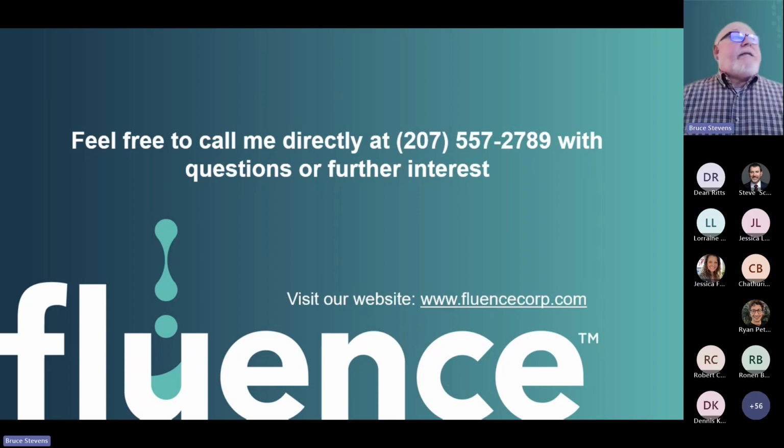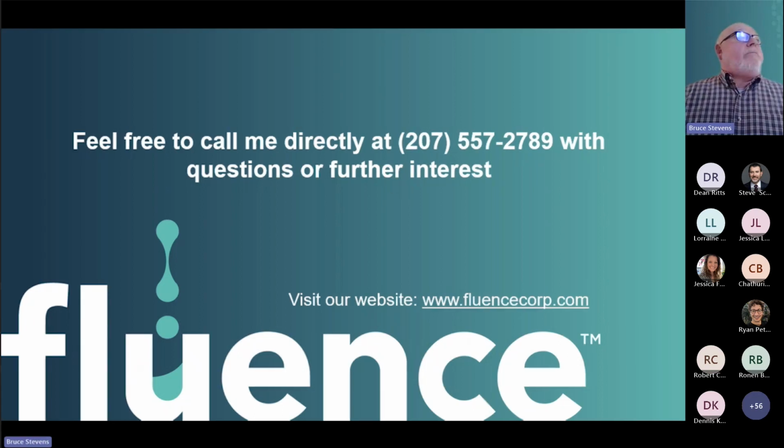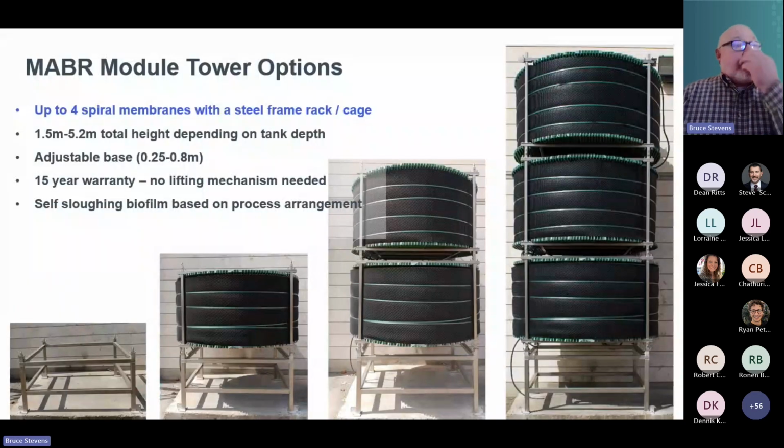One of the things I didn't actually mention in detail is that when we work with the towers, they don't just sit inside the tank idly waiting for flow to come through. Underneath these, we have coarse bubble perforated pipe engineered grids.